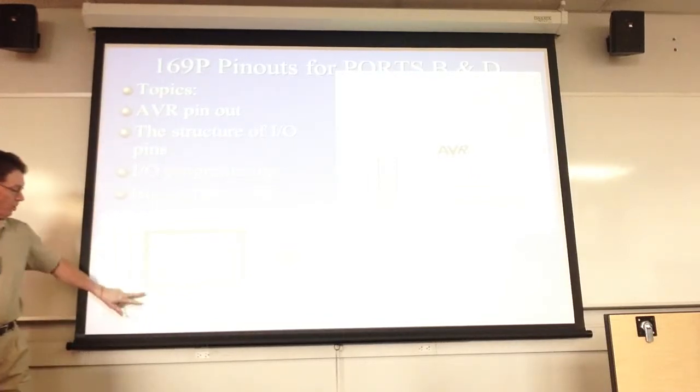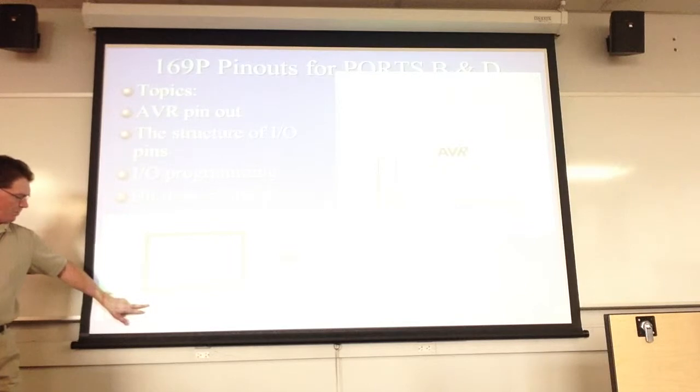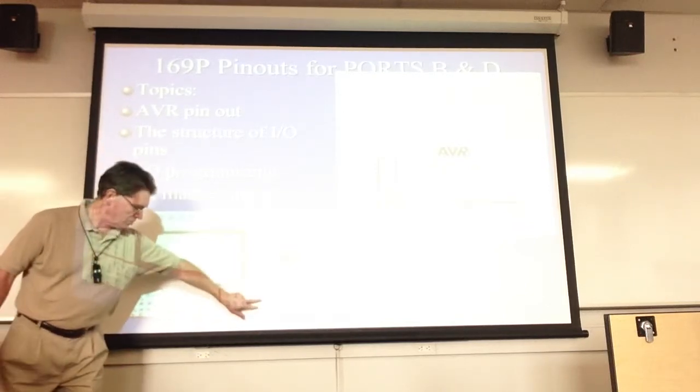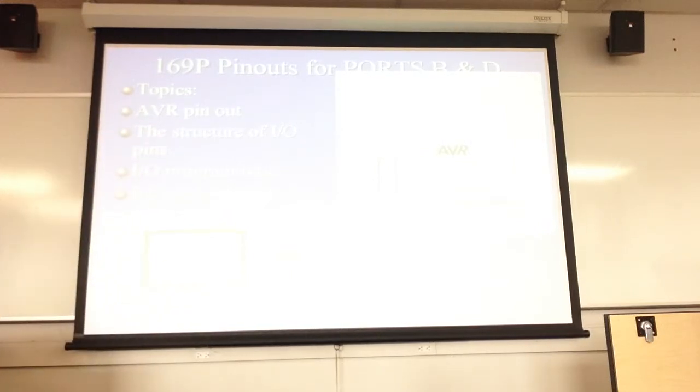Over here on both of these ports, you have, I believe, 3.3 volt VCC and ground on both of these also. So those 2 extra pins sitting there are for VCC and ground. And I'm going to tie some switches into this port over here on the right, just using an 8-pin dip switch. I'm going to be moving that up and down and turning some LEDs on over here. So I'm going to show you how to use these ports as not only outputs but also as inputs.